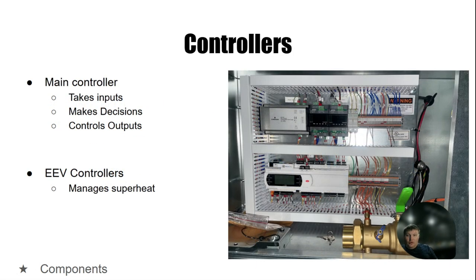We've got our controllers. We've got the main controller and an EEV controller. The EEV controller, all it does is manage superheat, and then the main controller is responsible for pump speed, enabling or disabling the EEVs, managing fluid temperature, and managing alarms.